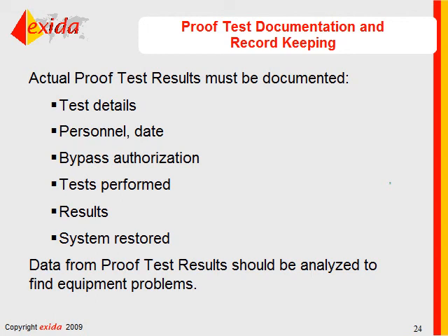If you run your calculations, that could be a drastic impact on the calculated average probability of failure on demand. You may have enough leverage in your SIL calculation where you say, well, I don't need to do this extra leak test. I'm fine enough, as it is with just a full stroke. So it all depends on the particular situation.